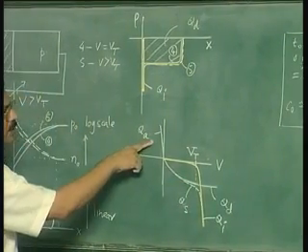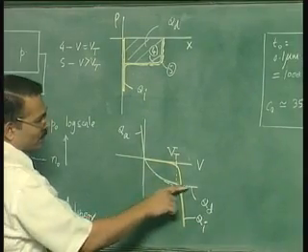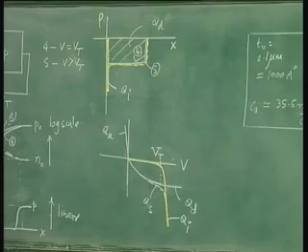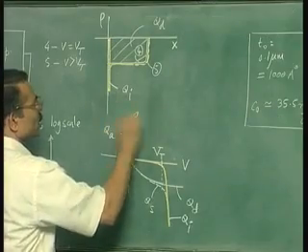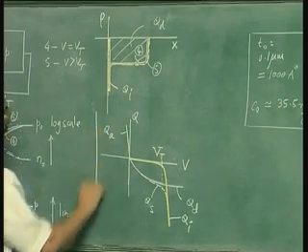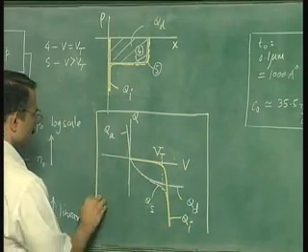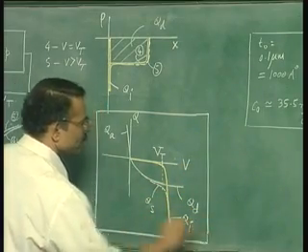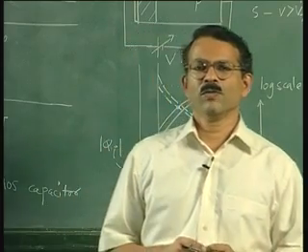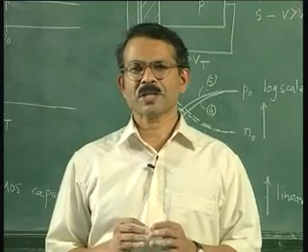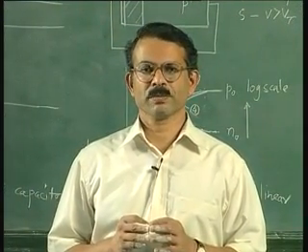We already have an expression for Qa as a function of voltage. So when you have the expressions for Qd and Qi versus voltage, we have the complete Q-V characteristics. So what we have drawn here is actually the Q-V characteristics that we said we wanted to derive for the MOS capacitor. So this is the charge in silicon versus the voltage. In the next class we will derive the equations for Qd and Qi as a function of voltage.